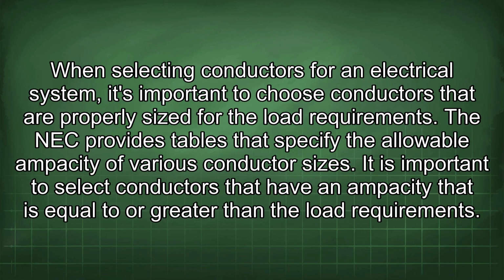When selecting conductors for an electrical system, it's important to choose conductors that are properly sized for the load requirements. The NEC provides tables that specify the allowable ampacity of various conductor sizes. It is important to select conductors that have an ampacity that is equal to or greater than the load requirements.